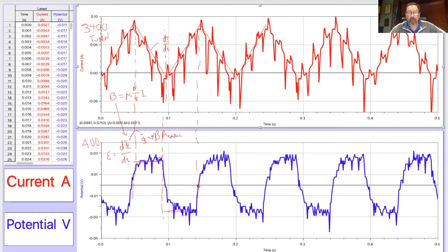And in principle, this would be kind of what's called a square wave all the way through. But remember, when we were talking about RL circuits this morning, we said these things don't change instantaneously. They go through what we call an exponential buildup. The shape of that curve is 1 minus e to the minus t over tau. And I think that's what you're seeing here for these electromotive forces. Each and every time the electromotive force tries to change in that coil, I get a shape like this, because certainly the coil has inductance, but because it's made out of real wires, it actually has real resistance. And so that's what we're showing here.